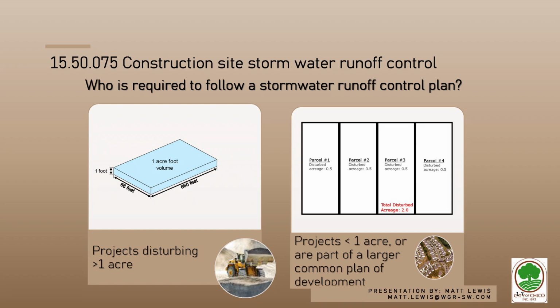That tends to be what these fall under, which is why your sites won't be required to have a SWIP, because a SWIP is 1 acre or more of soil disturbance. So, a lot of it is patios, pools, walkways, pretty minimal stuff. But it can jump into a SWIP if it's part of a larger common plan of development. So something to keep in mind.